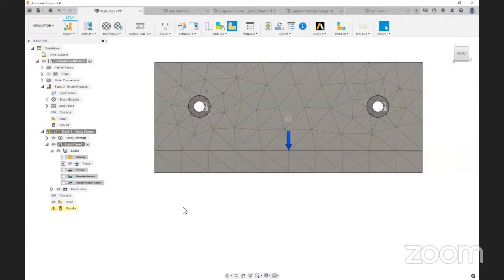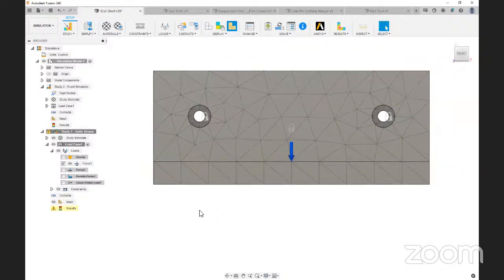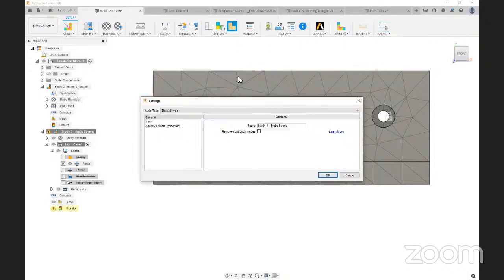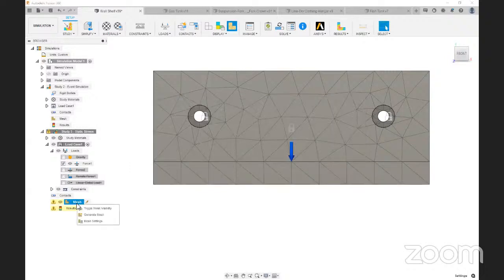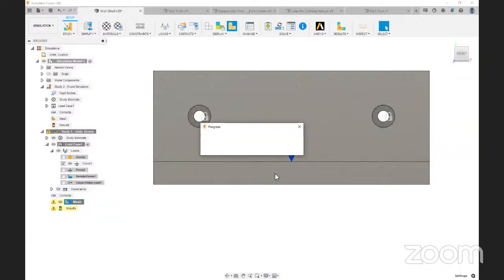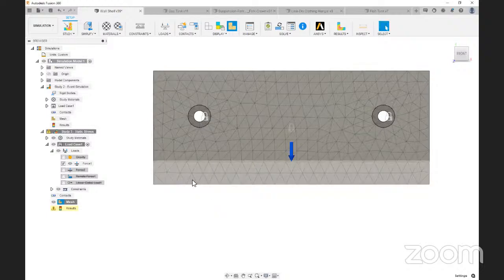This is after talking to our simulation experts, and they recommended having 2 to 3 different layers if we're bending inside of the simulation workspace here. One way to go about doing that is if we go up here to our settings, we can go to mesh, and we can lower the model base size to about 4%, 3% there. Right click on our mesh and generate the mesh again. And we'll see if it's going to be 2 to 3 here instead.